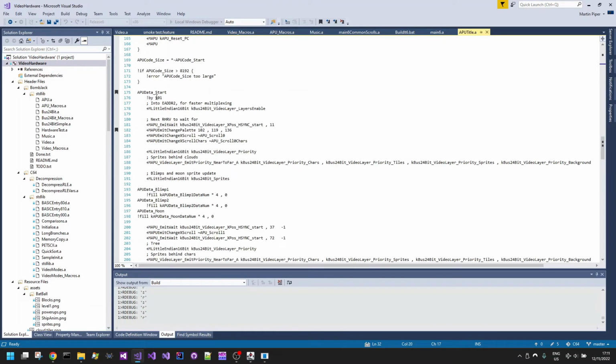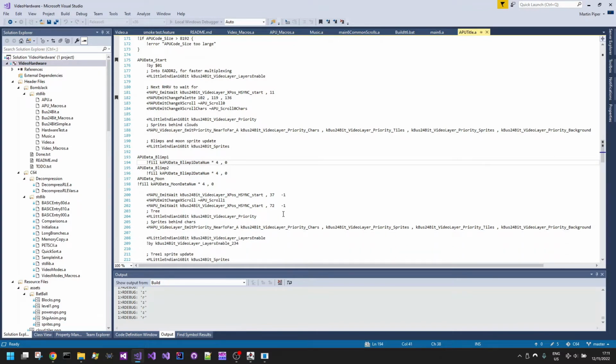And then down here, we define all of the data memory, which the APU usually accesses sequentially, although it's possible to have random memory access for the internal APU data memory if we so wish by resetting the internal address data pointers or loading new ones.